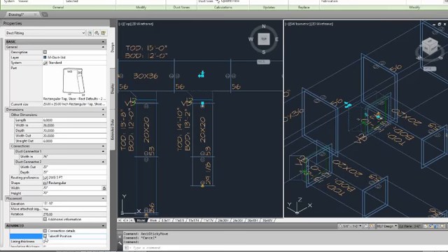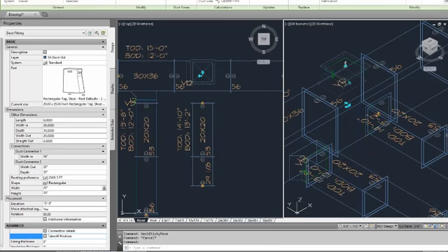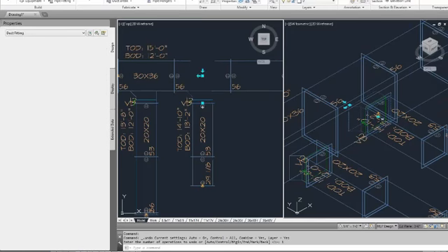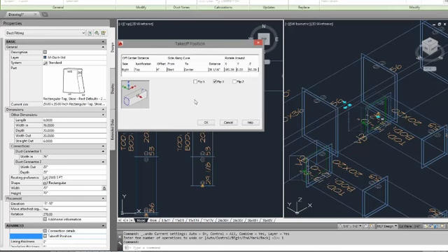If I need to change the position of that tap, if I need it to be on the top of the duct, then I can just come over here and on my side set at the top and hit OK. And we can see that that tap moved right up to the top of the duct. So once you understand the tap, the anchoring, and where to grab this position dialog, getting that tap to move to the correct position is very easy.